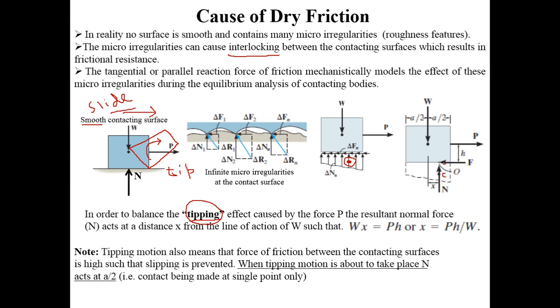So then how will it be confirmed whether the applied force will cause tipping action or sliding action? The point is that you are going to calculate the moment about this point O.